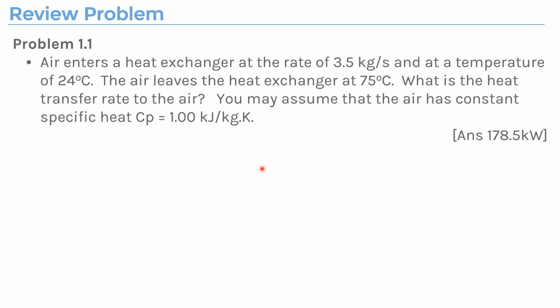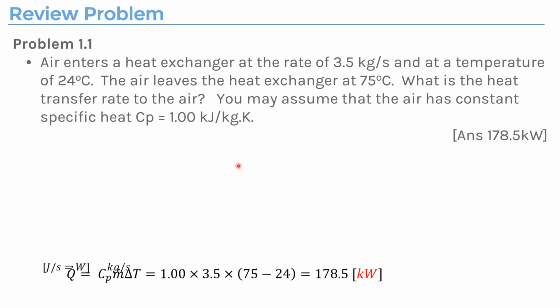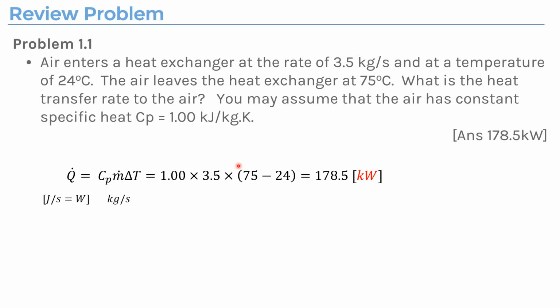So this is a really simple one because you only need Q equals m c delta T. Maybe I need to explain that this is quite simple because we always use delta T. So it doesn't matter whether it's in Kelvin or in Celsius because you will find out they are exactly the same. But in the test or the exam, students get confused because they see the units for specific heat. Sometimes it's listed as kilojoules per kilogram per Kelvin. Sometimes it's per Celsius degree.